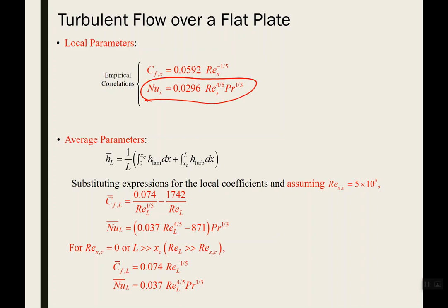If you remember, if you have flow over a flat plate, the Reynolds number is no longer constant. It's a function of x. So your Reynolds number will grow. At some point, as that boundary layer gets to a certain thickness, you're going to start to have turbulent flow, because the boundary layer has gotten so thick that it can't stay in this nice layered smooth form. So you may have flow that transitions from laminar to turbulent just from going from x equals 0 to x equals the full length of your plate.